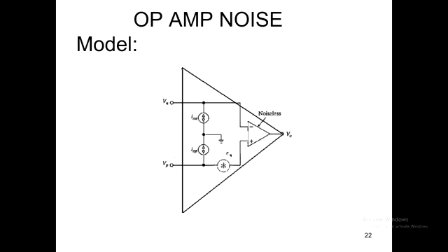Okay, now I'll just talk a little bit about op-amp noise without going into it in great depth. We'll just touch on it and we'll follow up with the heavy-duty questions. Similar to what we talked about with op-amps and the DC non-ideal behaviour, we can model the noise processes that occur in op-amps by aggregating them into equivalent generators.